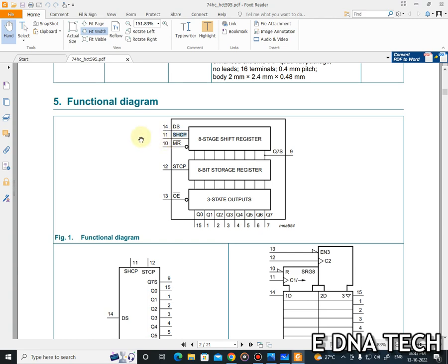So you want to give a clock pulse here. Here you can give data to this, and this should be enabled when we have completed our output. If we shifted 8 bits here, then if we give 1, the 8 bits will be delivered in this output. So this OE is an output enabler.